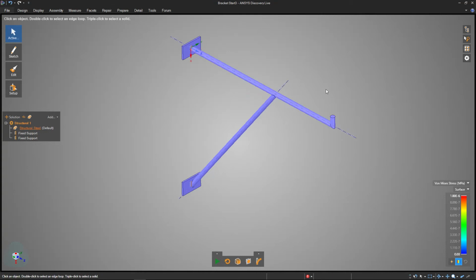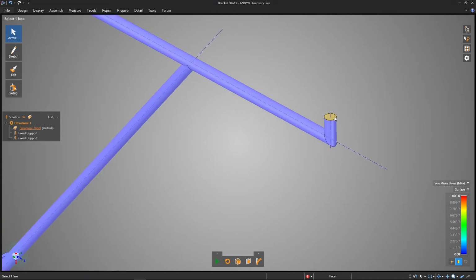So I'm going to escape from there. So if I click on this cylindrical face here, it's going to keep that force right in the center of this circle, and I can make sure that it's normal to the surface by default, so it's going to be going straight down. So new force there. For my students, I tell them to use 186 newtons because that's the value that we're using to actually test their fabricated final products. It's the weight of a 5-gallon bucket full of water. Default units here are newtons, so you don't have to explicitly put the N on there, but if you do, it's not going to hurt anything. Once I hit enter, it commits that.